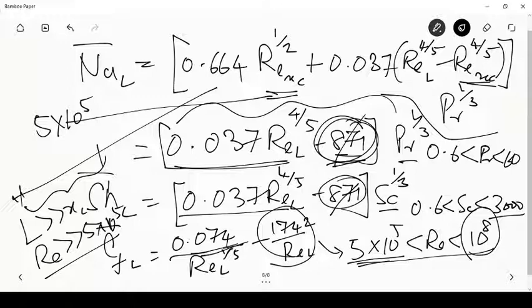So that is about calculating the average Nusselt number or average heat transfer coefficient over the entire plate. One small note about the temperature at which the properties have to be taken for calculating the Nusselt number, Prandtl number or Reynolds number, because the viscosity and sometimes even the thermal diffusivity can be reasonably sensitive to the temperature. For example, water from room temperature to close to boiling point, its viscosity changes by almost an order of magnitude. It's quite a large variation. So it's good to specify the temperature at which you calculate these properties rather than just leave it to choice.